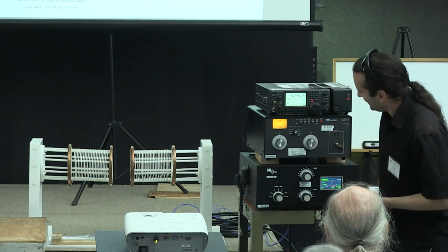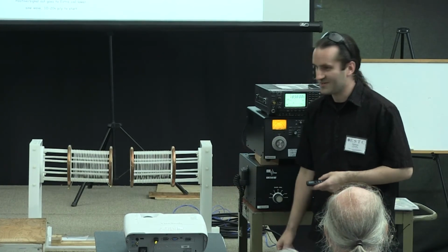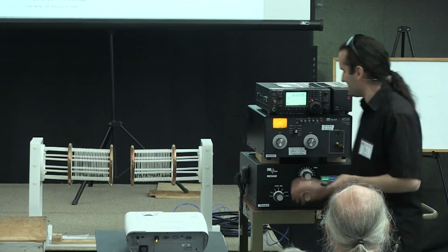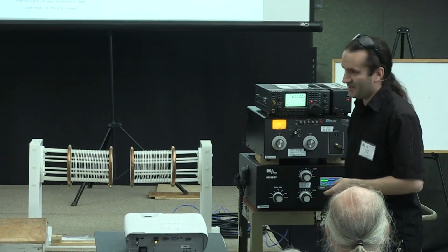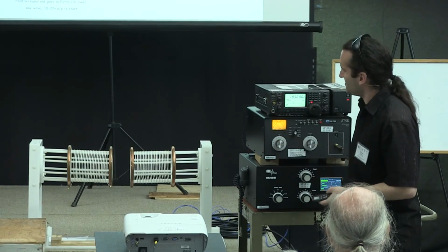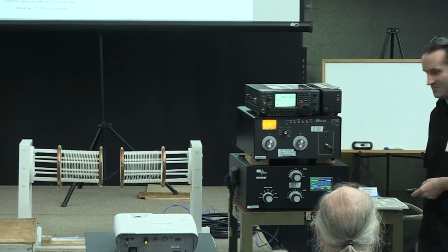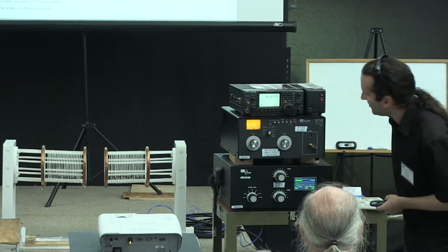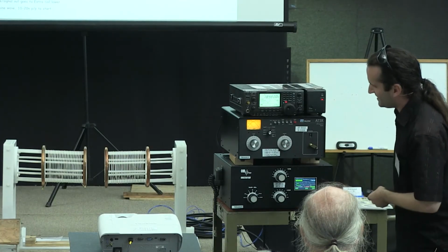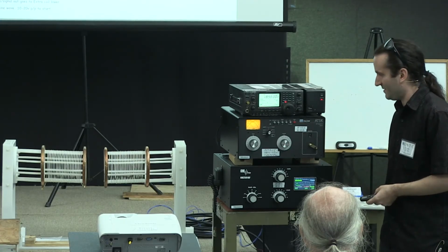Oh, yeah, it is working. Okay, so there's enough heat being generated by the resistance wire. You can see the paper start to singe from the power that's being dissipated. So this is the same setup that was going into the pair of Tesla coils that wasn't generating that kind of heat, that was safe to the touch several minutes later at almost twice the power that it was before. So here we're at 750 watts. It is going to change because the heat's going to change the resistance. But that gives you an idea of how power dissipates in a normal wire setup.